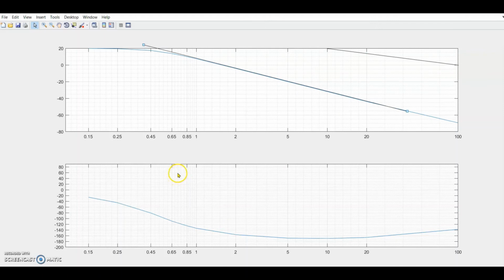So this is the minus 40 dB per decade line, and then just take this and try to fit this line somewhere here, because we are approximating the frequency response for the Bode plot. So it is around here. The plot starts with 20 and then it encounters the first corner frequency, so there is a drop of minus 20 dB per decade, and then it encounters another corner frequency, so there is a further drop of minus 20 dB per decade. So this is our Bode plot.